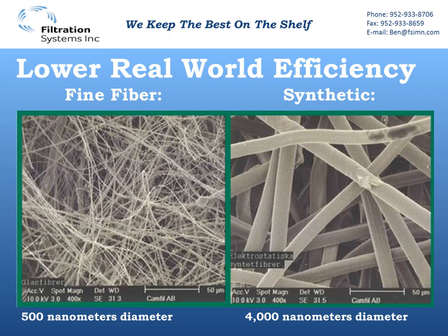The synthetic fibers often rely on a static charge to pull dust particles, especially the small dust particles, to the fibers. And once the fibers become loaded, now they're insulated, and that charge doesn't reach out and grab those small particles like it once did. Fine fibers rely solely on the media itself to strain those small particles out of the air. Once that charge is gone on these synthetic medias, the old rumor is that, well, the longer a filter's in service, the more dust it gets on it, the more efficient it is.